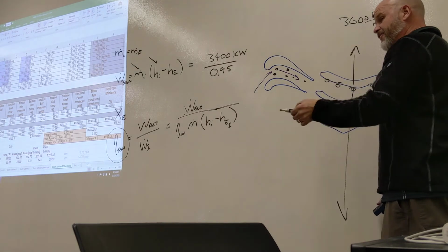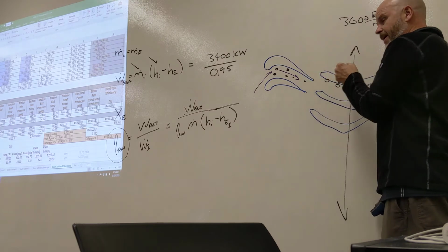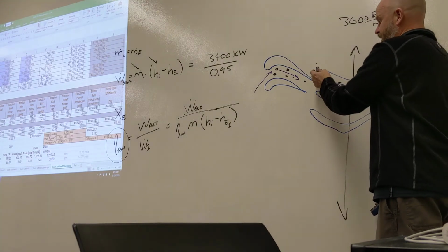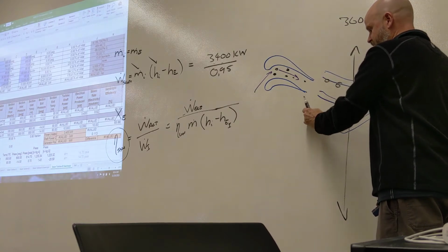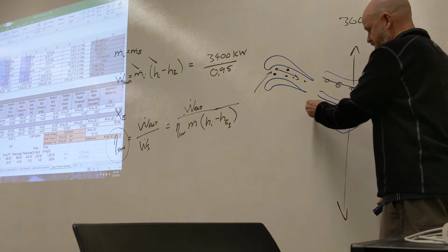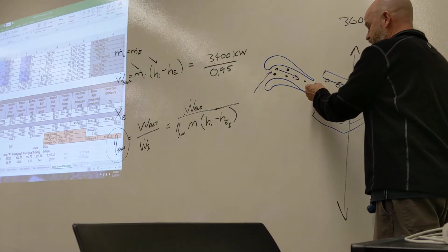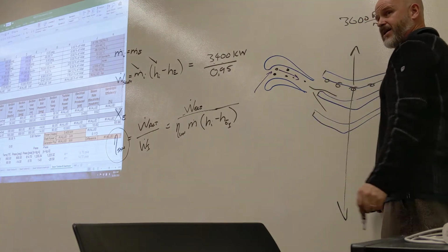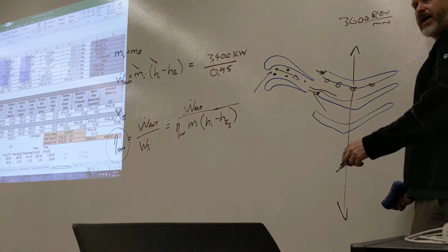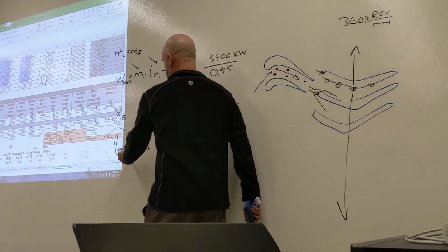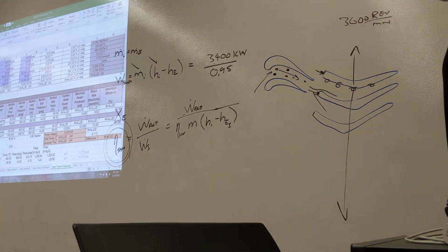There'll be a significant velocity difference between blade and droplet, and what will start happening is we'll blunt the ends of these blades, which means the steam that should be nicely flowing into these cavities now all of a sudden has an opportunity to blunt against a blade, which also negatively influences efficiency and life of the turbine.